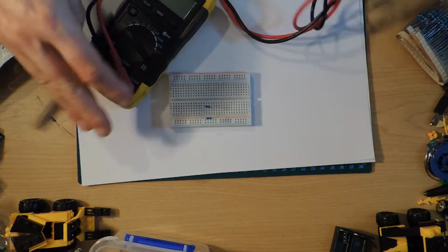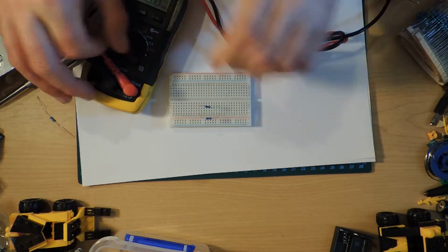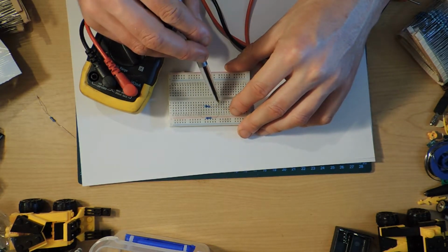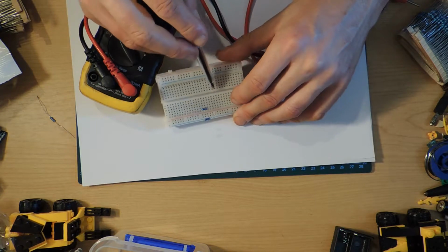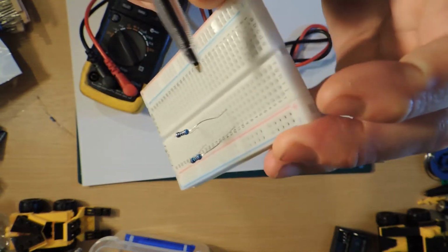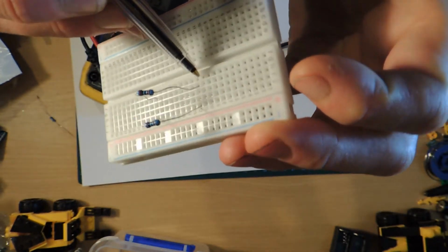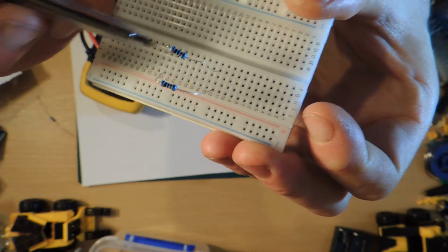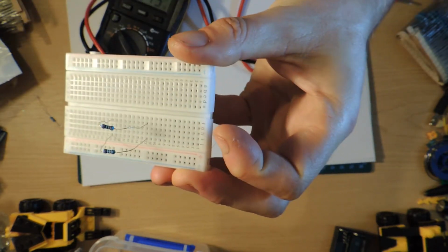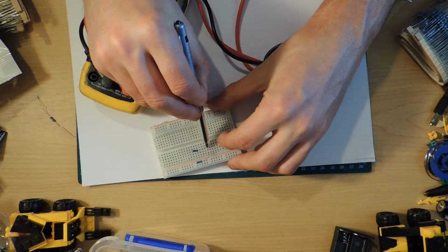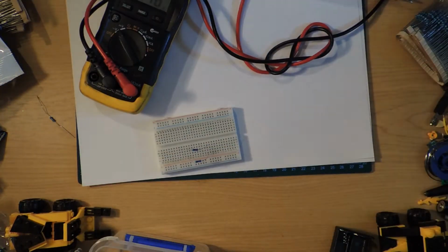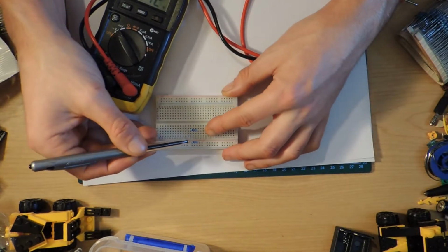But this is a multimeter, so we'll just do some multimeter fun. Here is a good way of putting two resistors in parallel on a breadboard. The little pins, I'm going to bring this up close, go in the same line. In this case they're in line 12, and in this one they're in line 20, and so they are now in parallel because everything here is connected. And so, bringing back my little diagram, these are 10,000 ohm.